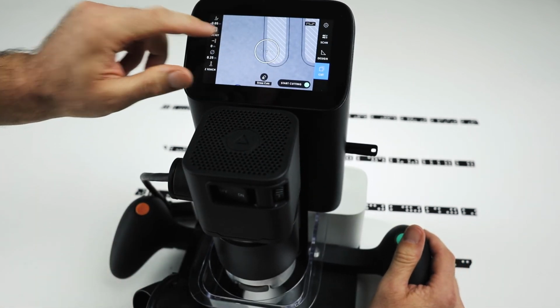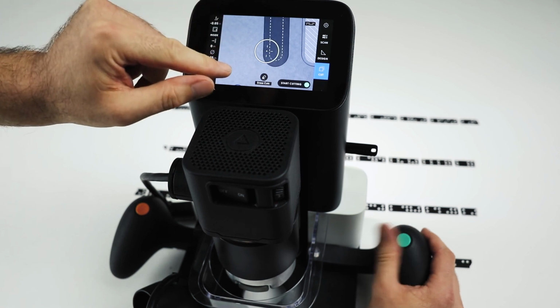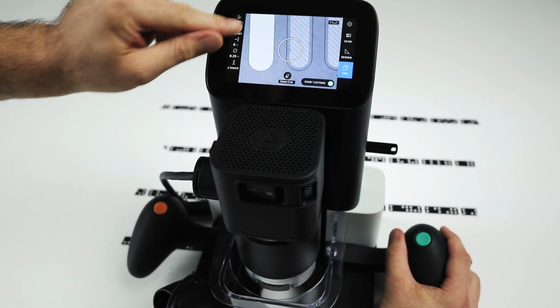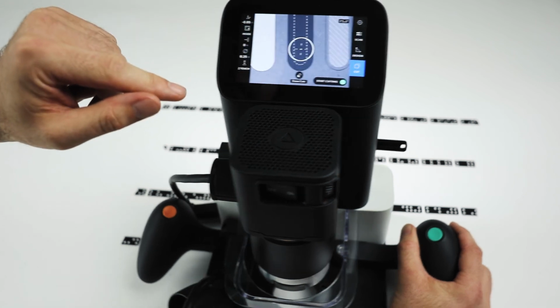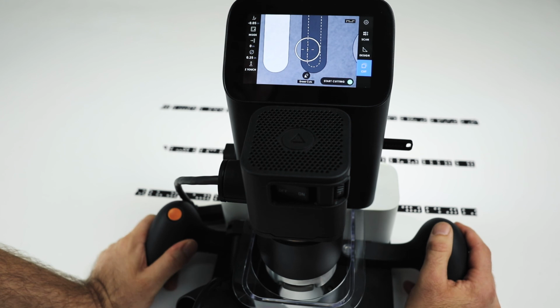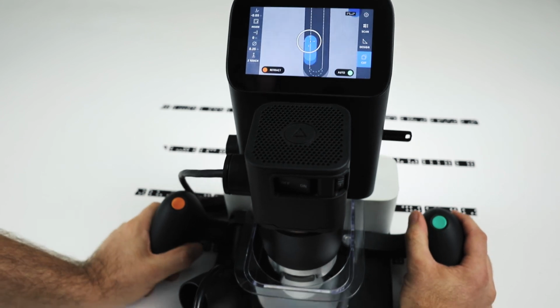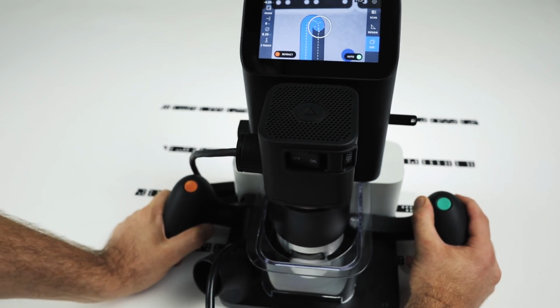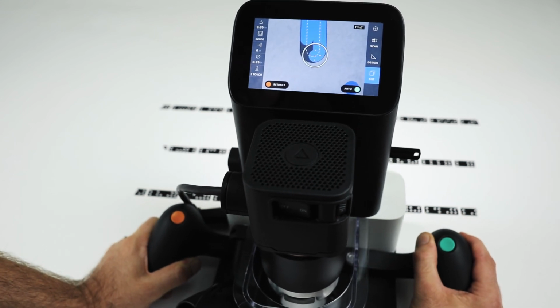I'm actually going to change these to inside lines. I'm going to do that to all 3 of them. You'll notice it highlights as a pocket, and I can tell it to be otherwise. So it's telling me which direction to go. Plunge. Around. So you'll see we remove all the material.